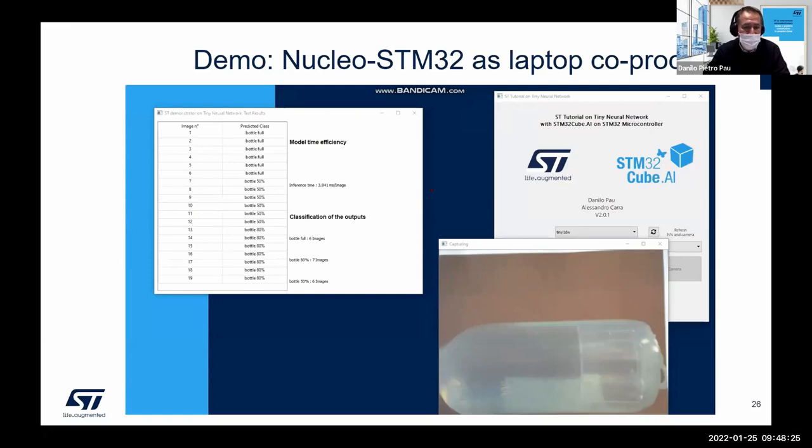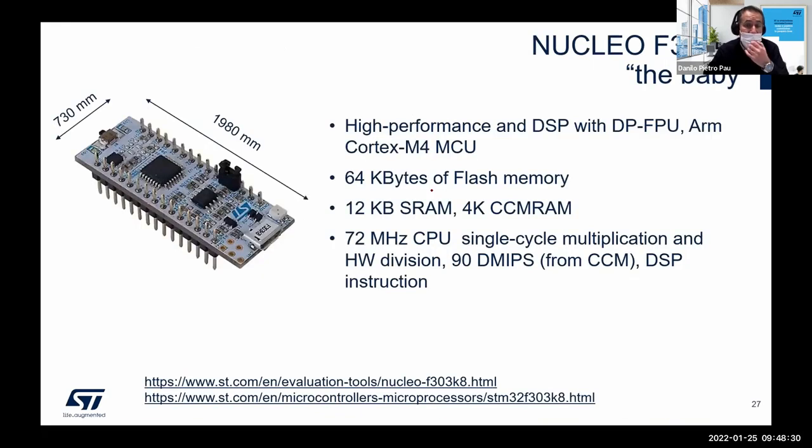post-training quantized pipeline, between the ones that I showed before, or I can, thanks to the exercise of fine-tuning the parameters and the mix of layers, go to an even more challenging tiny board, which is featuring an STM32F3, which is a Cortex-M4 with 16 kilobytes of RAM and 64 kilobytes of flash, very tiny.